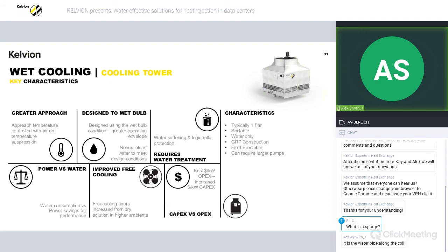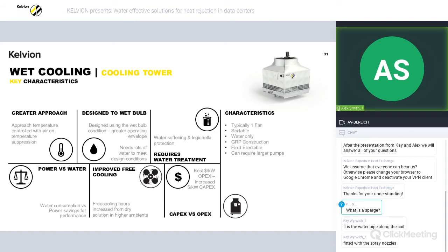So cooling towers, though they often require many times more water than adiabatic systems, offer the best free cooling potential and power reductions. However, cooling towers typically require a plate heat exchanger, which increases the required approach, as discussed briefly earlier. Sometimes this can limit operation due to the impact it has on the thermal profile of the process.